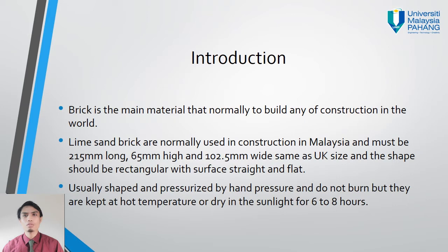The shape should be rectangular with a straight and flat surface. This type of brick is non-flammable. The brick only needs some pressure and to be kept at a hot temperature or dried in direct sunlight for 6 to 8 hours.